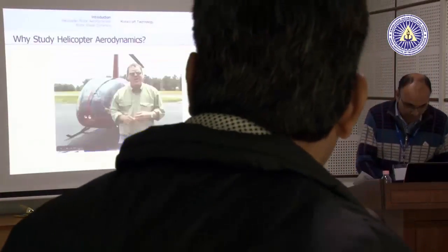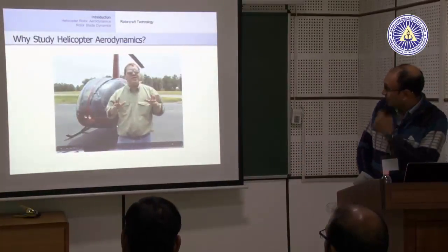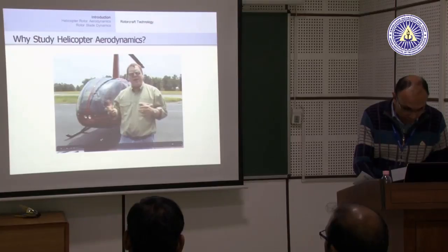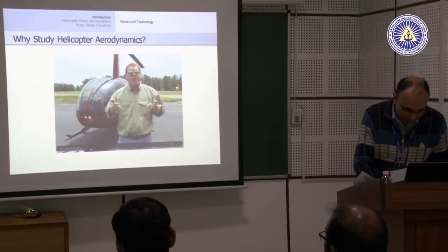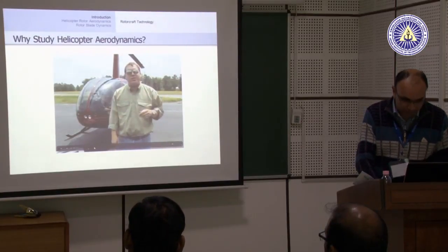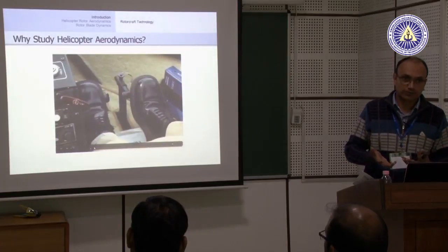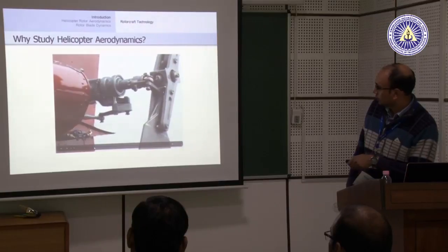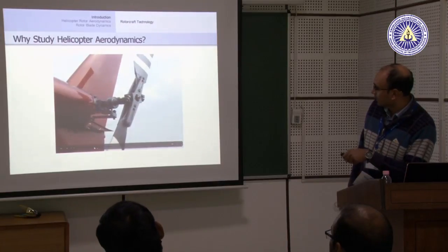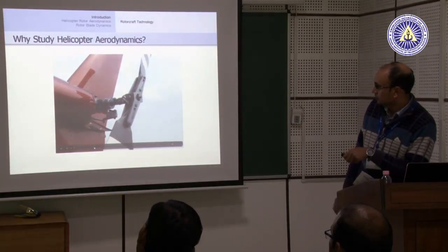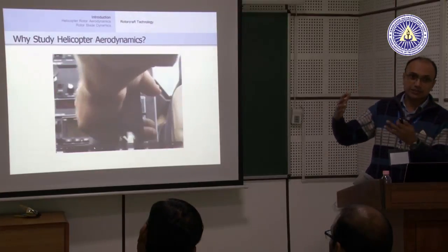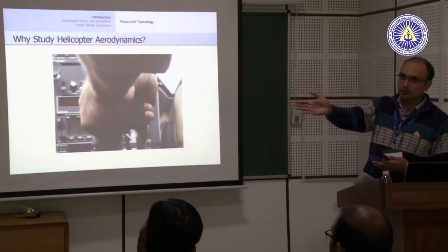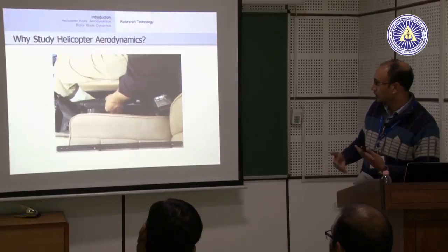So here is now a very nice small video where the person shows you how a swash plate functions. This is important for us because we have to understand how a helicopter is actually flown. Right now he is operating the pedal and showing how the pedal changes the collective pitch of the tail rotor blades. This is how you can change the thrust that the tail rotor is generating, because that will allow you to turn the helicopter in a particular direction, so make the helicopter yaw.